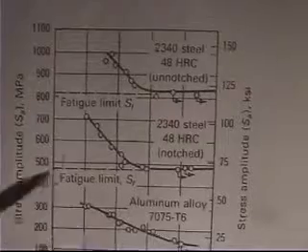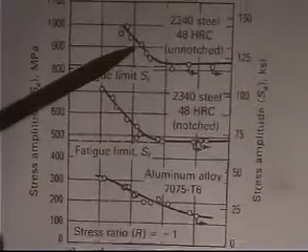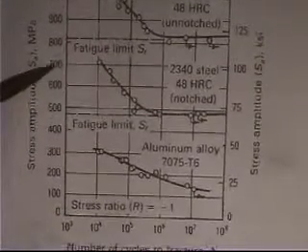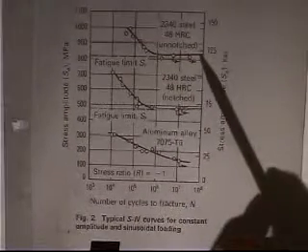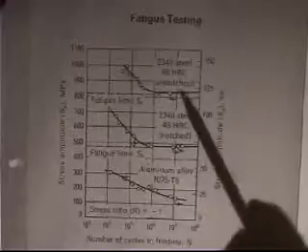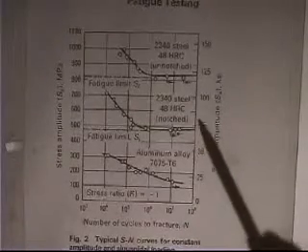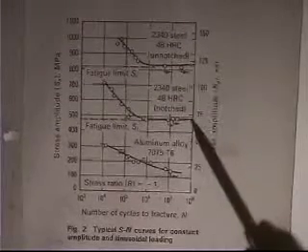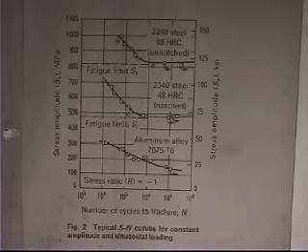If you're talking about aluminum alloy, they haven't changed the origin. This is on the same scale. So a high strength steel, which 700 megapascals is 100 KSI. So if you go over, you're at 125 KSI fatigue limit. That's a pretty high strength steel. This is not landing gear type of steel, but it's the type of strength level that you're approaching, the type of strength level that you'd have in a landing gear for an aircraft. Here, if you put a notch in it, you can drop your allowable stress by 40%. So someone takes a high strength piece of steel and you put a file notch in it, you're liable to get a fatigue crack.